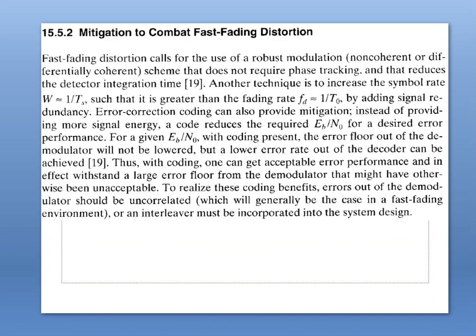An interesting filtering technique can be provided for mitigating fast fading distortion and frequency selective distortion. The frequency selective distortion can be mitigated by using an OFDM signal set. Fast fading, however, typically degrades the conventional OFDM because Doppler spread corrupts the orthogonality of the OFDM subcarriers.